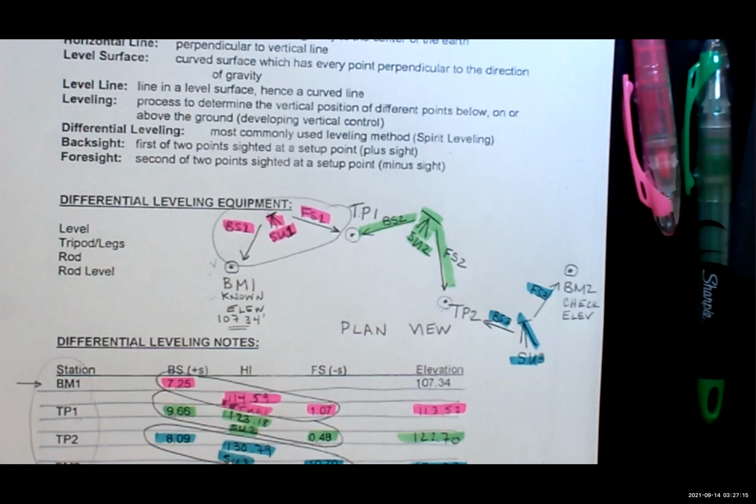How about if you made a mistake somewhere along the line? Oh man. So when you survey, you don't just go from a known elevation to an unknown one and say, oh yeah, it's 100 feet, I'm totally confident. You actually do a loop and close it. You start at the benchmark, you put in your 100, you come back and go, good, I'm fine. If you come back and you're off by a certain amount, and we'll talk about error, you've got to do it all over again, right? So that's why you have to be really meticulous. Time's money, right?